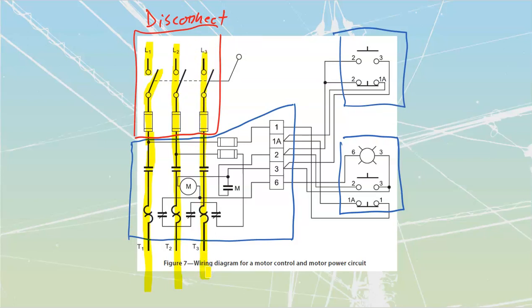You always want to trace through all of these all the way just to make sure that there are no surprises. Remember that if we're dealing with single phase, sometimes we loop that extra conductor back up. We have installations, we talked about this at the very beginning, where we come out of here and loop this back up to the top of a contactor or something like that. Not in this one, I'm just warning you so you know when you double check it. I know it seems like you shouldn't have to, but it's wiser to do so.